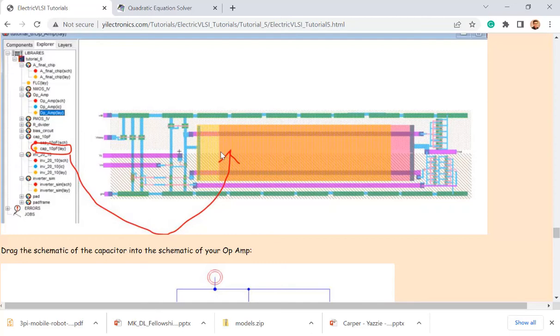Why? Yeah, that's one part of it, important. So usually you want to make the connection pretty long to cover all the cap, the poly material, and that's metal 1 to poly 2 to metal 1. And if you make it longer, then it's going to short to the rail. That's a metal 1, right? That's a via to metal 1. If you make it over here, then it's going to short to the rail. Just keep in mind.